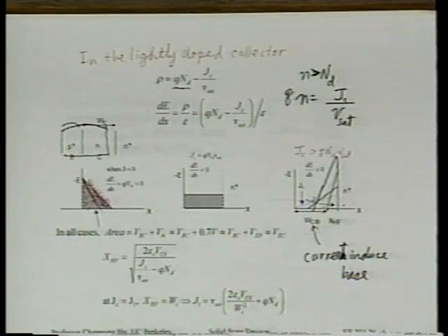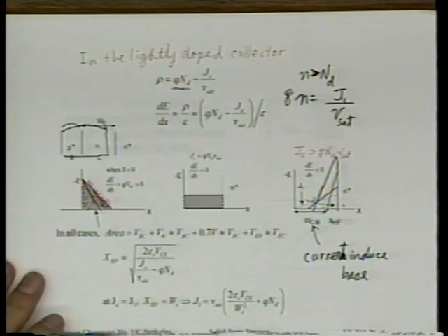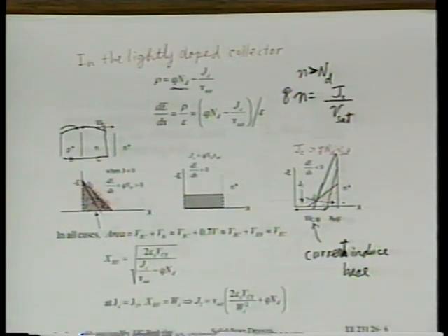Okay, but to be honest, we're not as concerned about the gain drop. We're more concerned about speed drop, because we're really trying to get the highest possible speed of a bipolar transistor, right? So that's really what we talk about with the Kirk effect. The remainder, I really don't have to go through. I'll just tell you what it is. We don't have to go through it. And if you are curious, maybe you want to, all right, we will do that, okay?